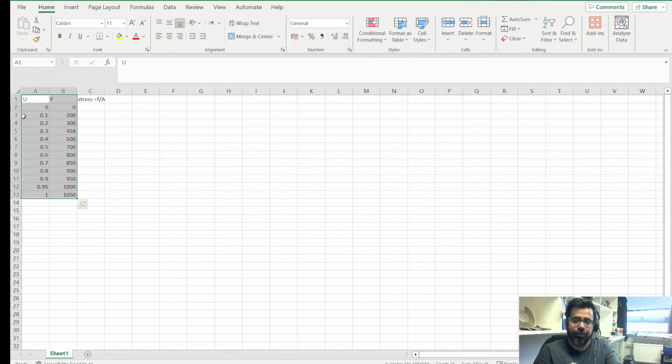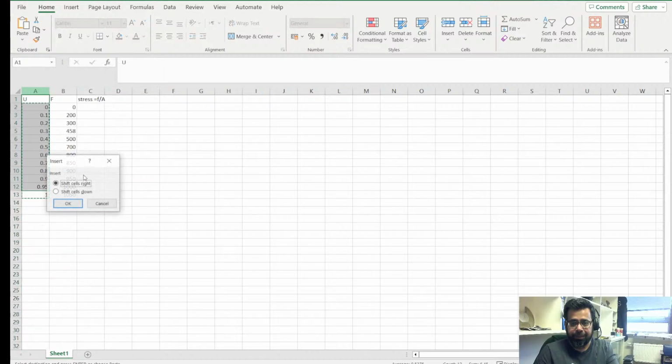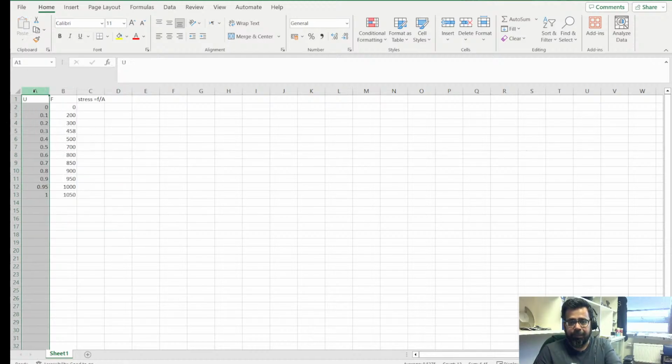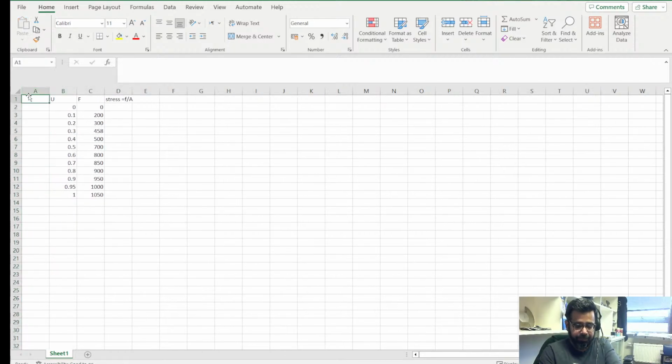So if you have this data and you think your test is displacement control, then you should apply the displacement using this kind of increment. So if I were you, I would just copy this. And let's say I have another column here, and that is time. So let's say time started from 0, and then it went up to 0.25, 0.5, and so on. Something like this. The time looks something like this. Okay, so this will give us my amplitude function.